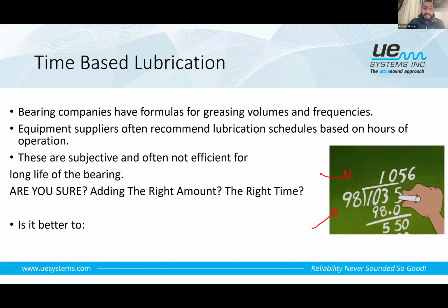So this philosophy, this strategy is based on calculation, based on numbers, based on speed, based on temperature, based on a lot of things, and also it will not be 100% efficient. I'm not 100% sure that I'm adding the right amount at the right time. That's why, following the time-based lubrication, we still face some problems related to over lubrication and some problems related to lack of lubrication.